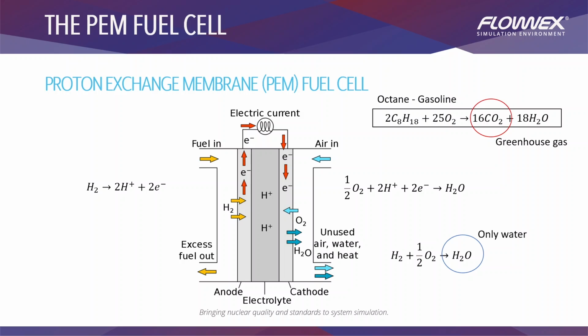In the PEM fuel cell, the operating temperature is quite low compared to other conventional fuel cells. However, heat is being generated during the chemical reaction process. If this heat is not properly removed, the fuel cell stack temperature will increase, which will essentially damage the electrolyte and decrease the rate of proton movement. This means that proper thermal management of the fuel cell stack is necessary to ensure high performance.